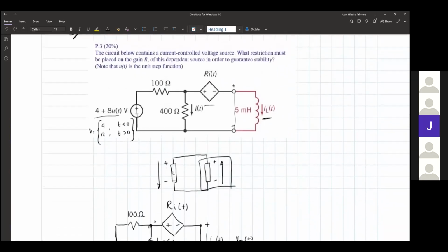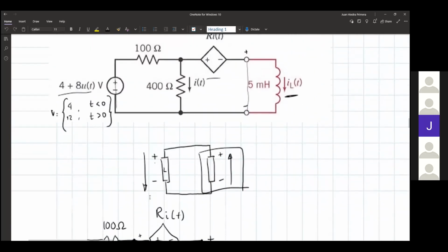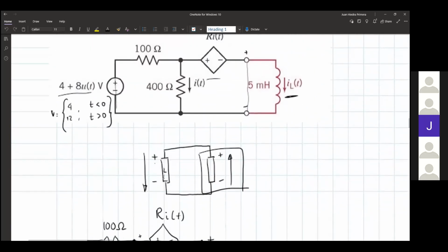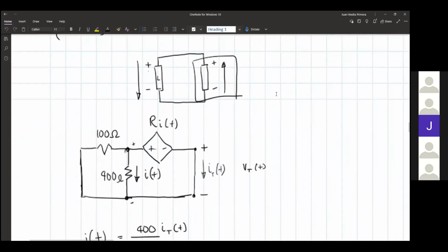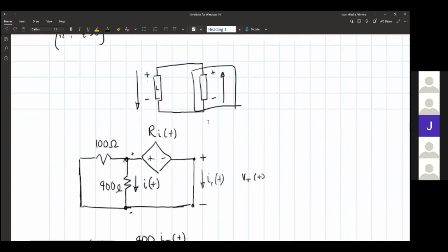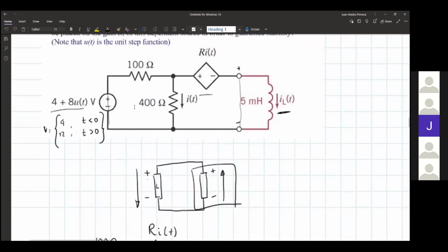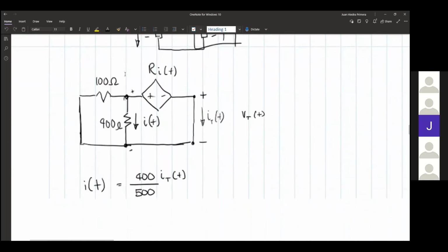We want to set up the circuit in order to have a load with a current. So in this case, we want to turn this load into a short circuit and find its short circuit current. So we short circuit the voltage source here, and we try and find the current traveling through there.